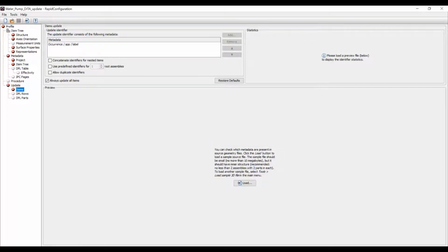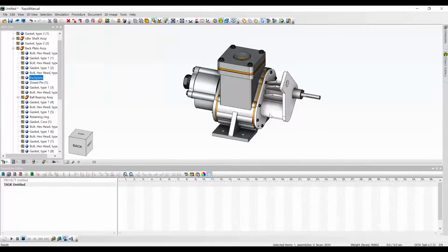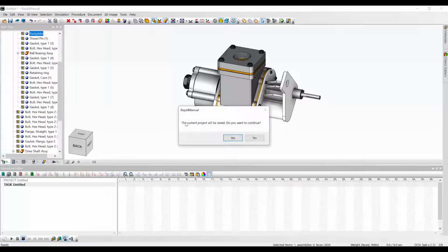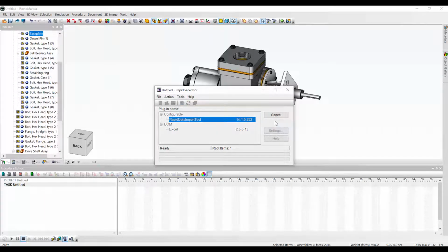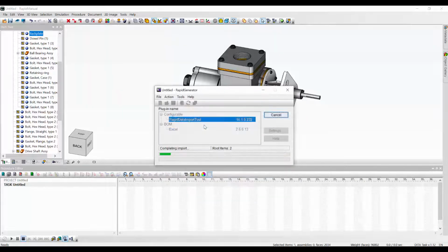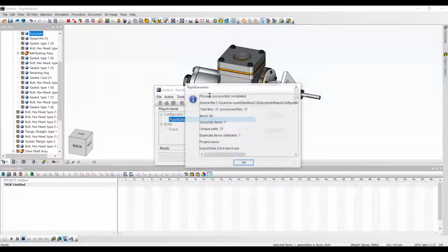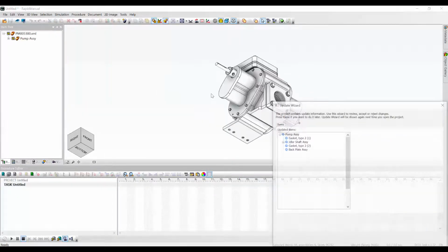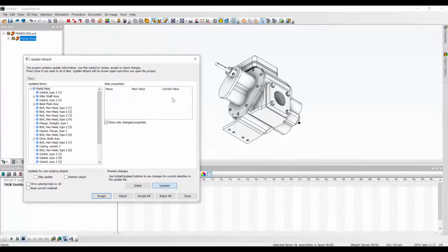This can be the case with certain formats that do not support various metadata properties, or when designers of CAD data have not included such metadata. Here, really only 2 items are being updated with the source data. However, this option forces all items to be updated, which can be a good solution once again when source data does not have enough metadata required to trigger an update.